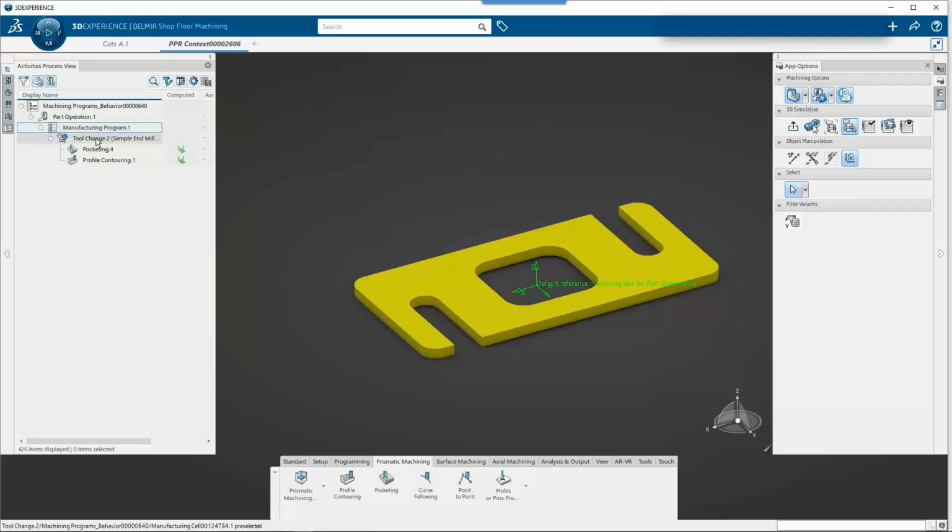One is the very basic, like as I look at each operation, it just does the material removal. If I click the play button in the middle of the compass, then I'm kicking off a more advanced simulation tool. It's going to catch the same things, but just keep in mind that the play button up here, as we get into later lessons and we talk about multi-axis machining or mill turn or things like that, I want to do more advanced type interrogation of how the machine and the virtual twin actually works.